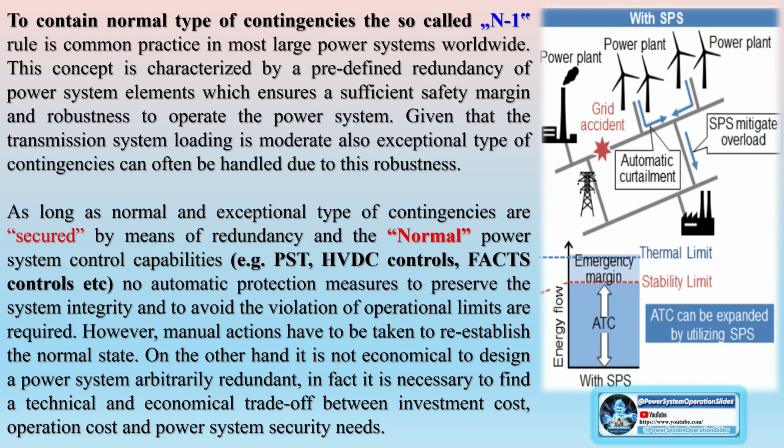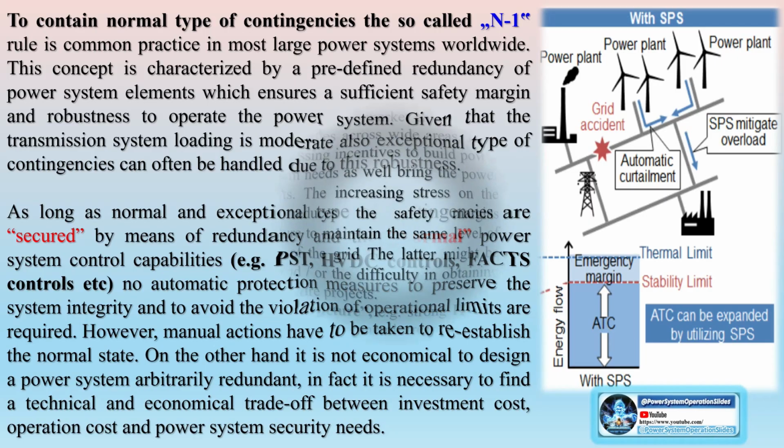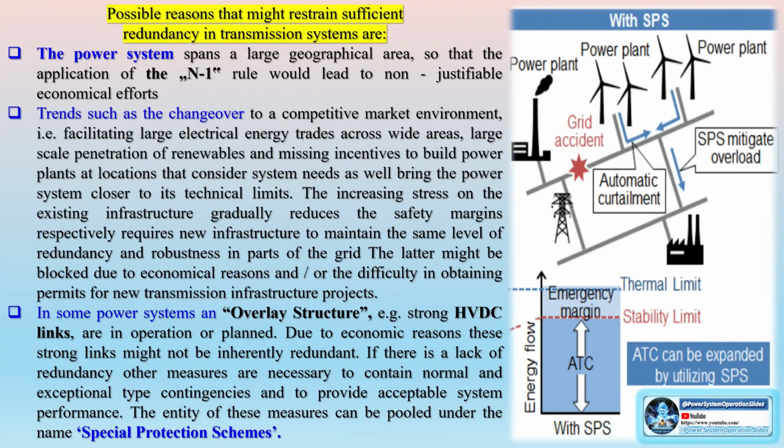Voltage instability is the failure of the power system to maintain steady acceptable voltages at all buses in the system. Remedial actions include changing of generation, automatic shunt switching, control of series compensation, blocking of tap changer position of transformers, undervoltage load shedding, etc.